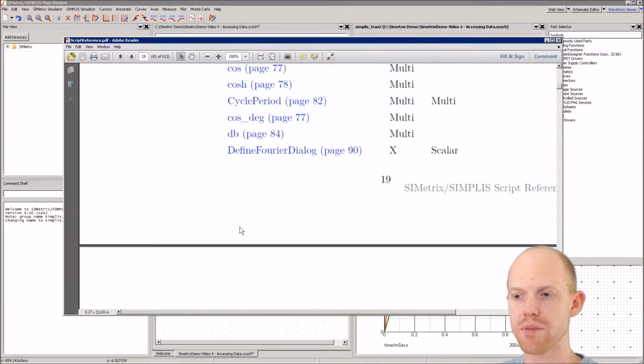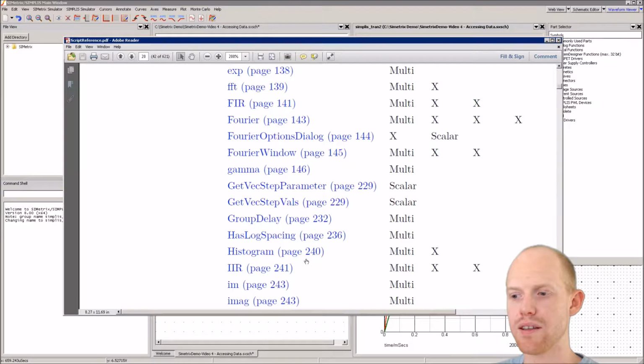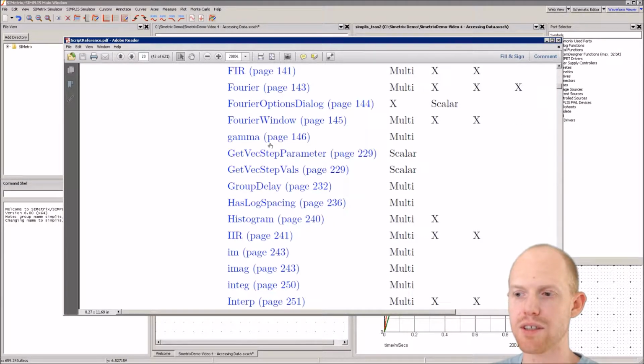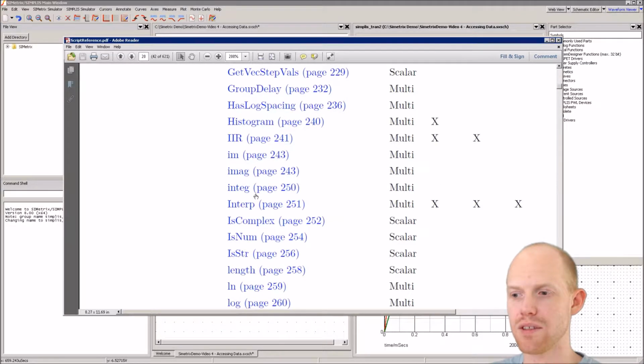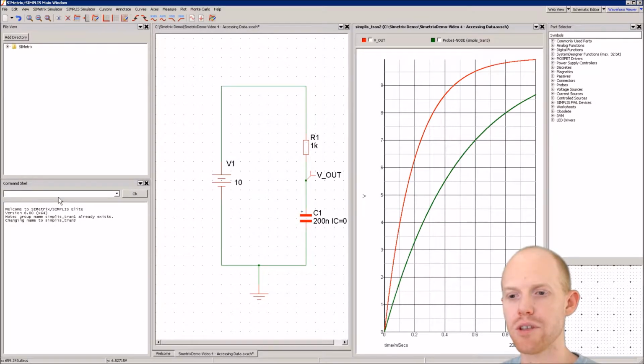So there's all kinds of built-in functions you can use to manipulate the data, and these functions are not in the scripting language. They're lower level functions that are really fast, so you definitely want to call these functions before you start writing loops in the scripting language, because those are hundreds of times as long. Now we probably want to start by seeing what groups and variables are available, so you can do that with the display command just in the command shell.